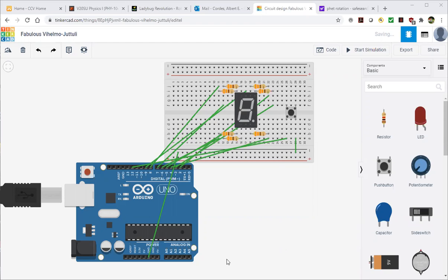And first of all, the pins are on the side of the 7-segment LED, and you can see from this diagram how they're numbered. So they go 1, 2, 3, 4, 5, 6, 7, and then pin 8 is on the bottom across from 7, and then it goes up 9, 10, 11, 12, all the way up to 14. Now this one, B, is the particular 7-segment LED that we have.